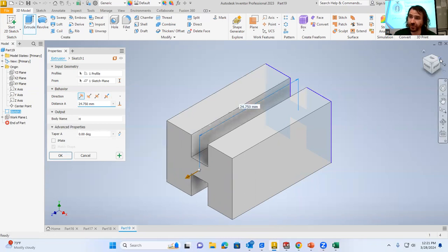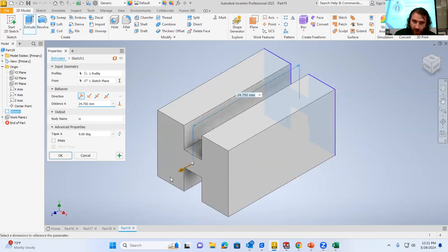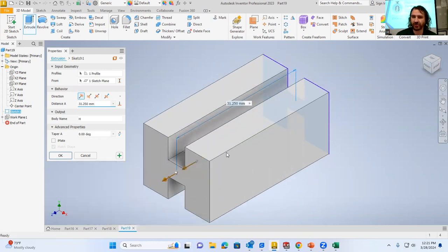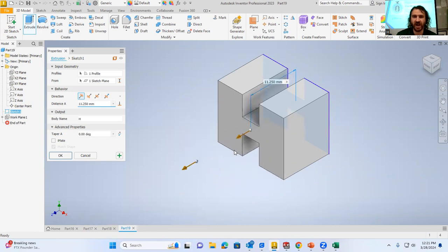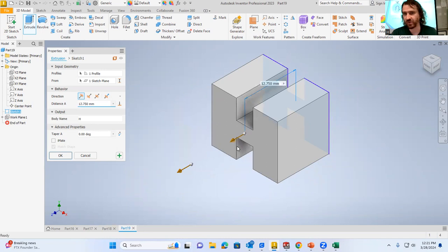And with the extrude tool, whatever the profile starts out as here with this shape is what it's going to end as on this other side of the extrusion. And it's just going to depend upon how far that extrusion is. We can adjust the size, all that we want, and make it any size that we really need, by changing this distance number that is here, right?